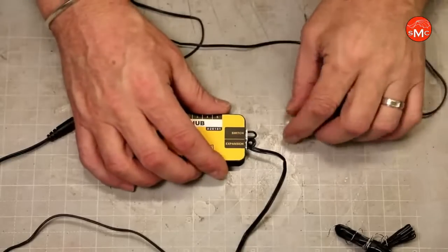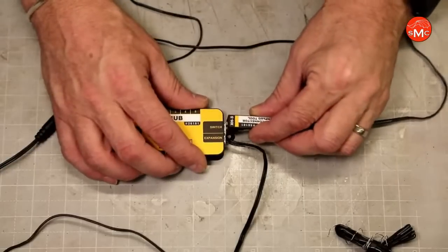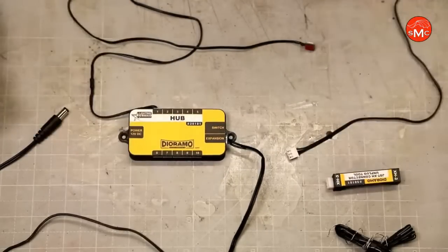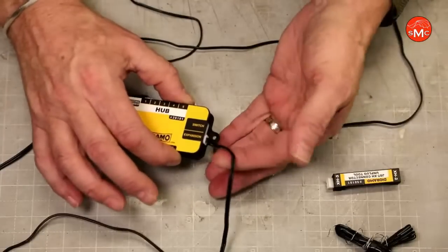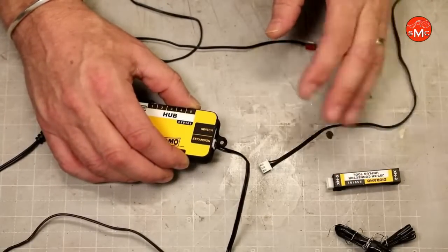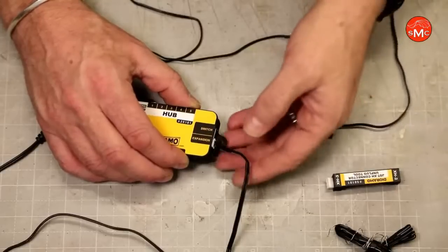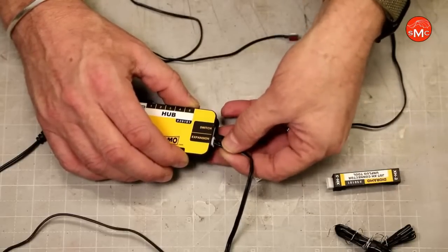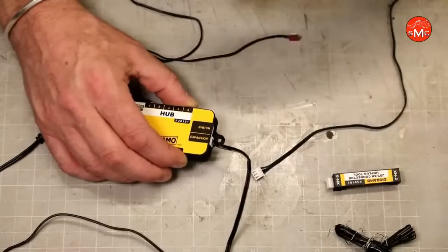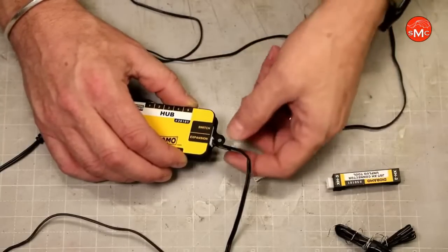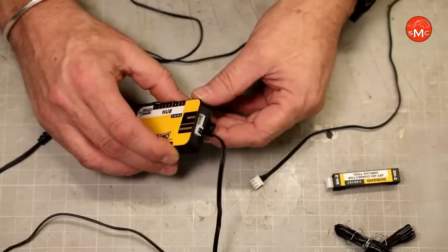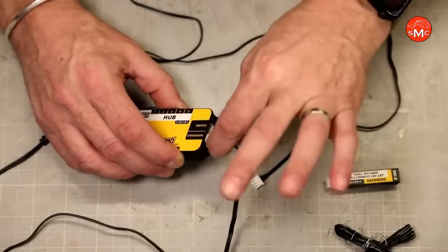So what I do is I take my puller, and one of the tests that you do in quality assurance is you will take the wires, and don't do this. It's not designed to be done this way. But in QC, you will just take these wires and pull. And there's different types of pull. There's the yank, where something falls off, that simulates that. There's a slow pull and stuff like that. I just did a slow pull. But the point is these aren't supposed to come up just by hand. You're not supposed to do that.